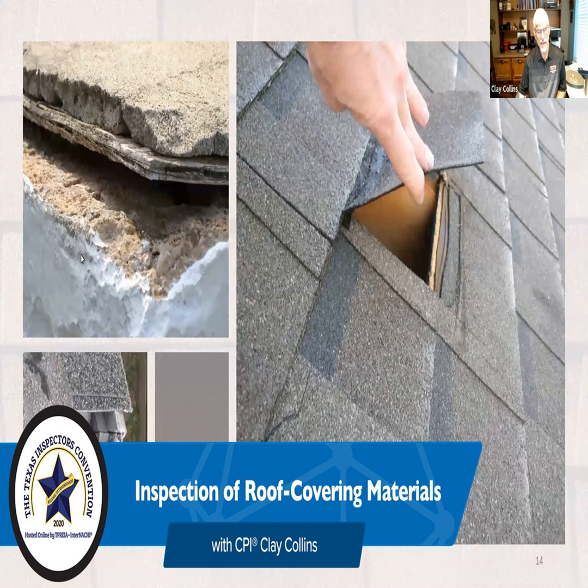How the roof structure is built is critical. Each piece of that is important. The framing, if the framing doesn't support it, you're going to have failure of the framing, which can affect roof cover, which affects leaks. The sheathing, we're going to kind of go into some detail there. The underlayment, if it's improperly installed, we'll talk about that.